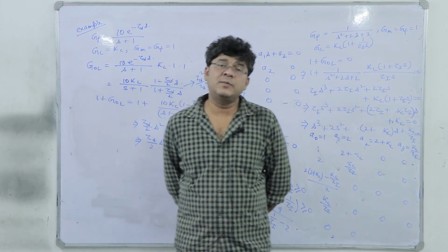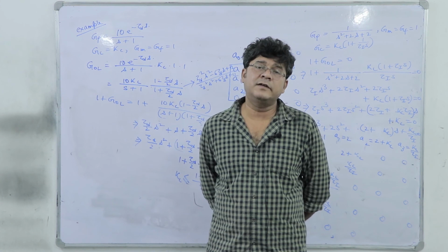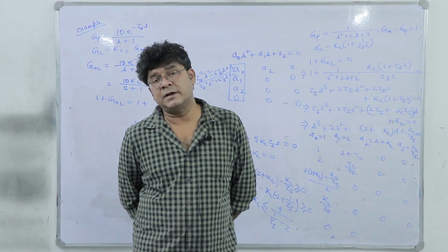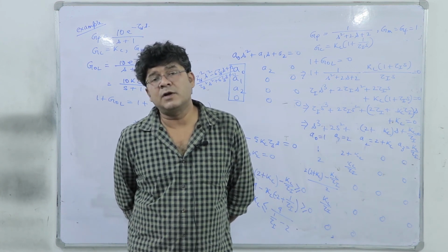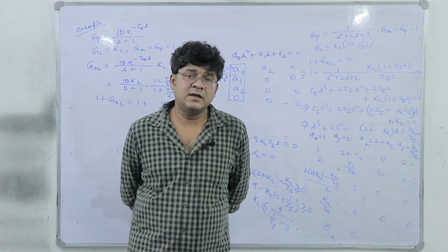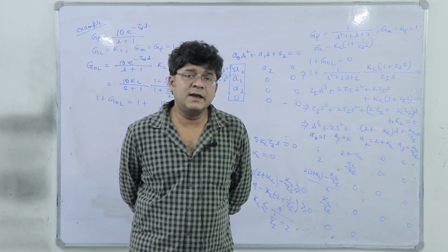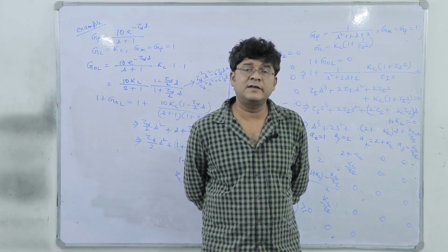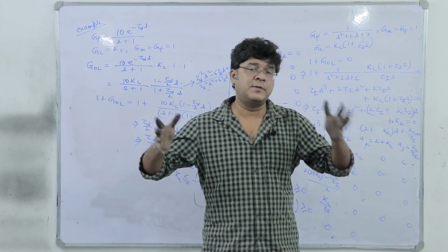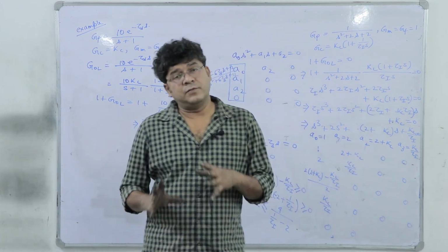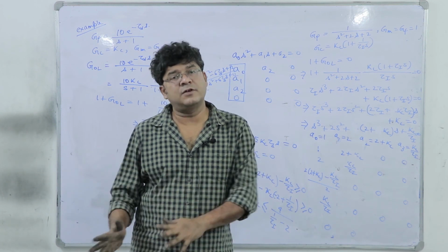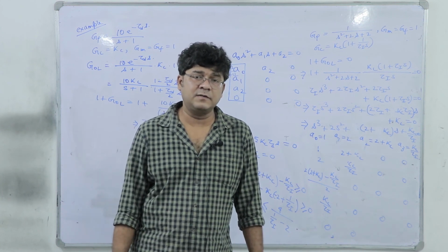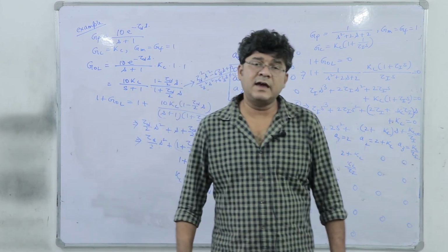Like a distillation column, if I change the input or the flow rate or the reflux ratio or something else, how the distillate composition or the bottom product composition is going to change, right, dynamically. So, it is not very easy to determine because there are always non-idealities associated to tray hydraulics, to vapor flow, to distribution of the liquid and vapor over the entire tray. So, definitely we will go by a model, but we have to cross check and verify whether we have got the exactly accurate transfer function such that we can go for designing of a controller.